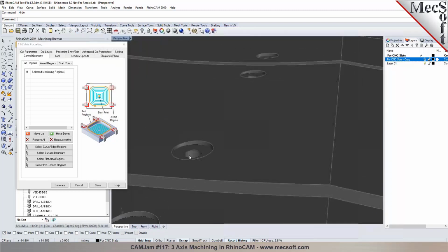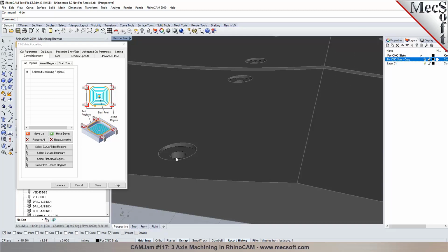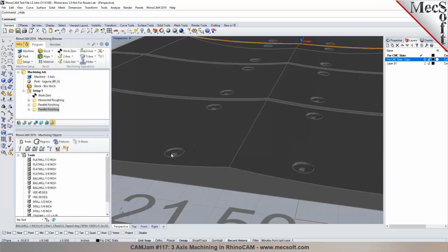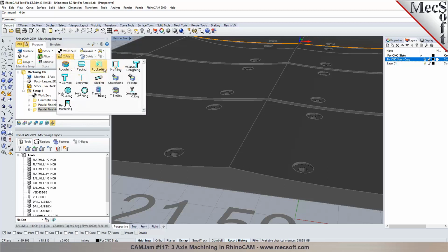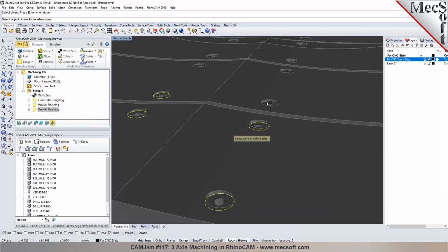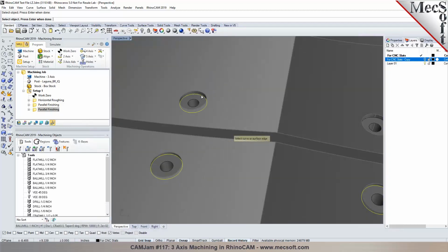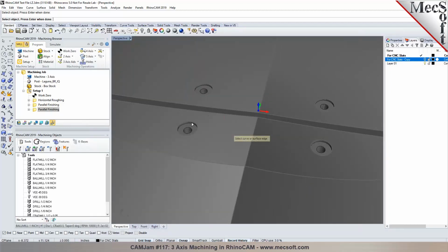So we want to make our selection process as easy as possible, right? You can do select by diameter or select by range. In Rhino, you can even script certain things and do select by diameter. But here I'm just going to go ahead and do a simple pocket operation. We'll just go pick. You can see because I locked the other objects, your selection is a lot easier. Just a click. It's not going to even bring out the selection menu. That's the beauty of working with an integrated CAD system, you can take advantage of all your selection tools in here, right?